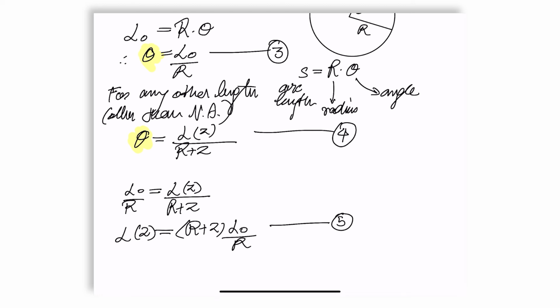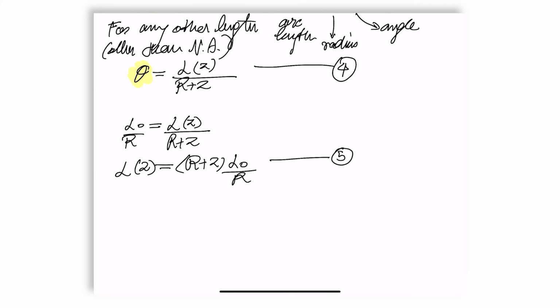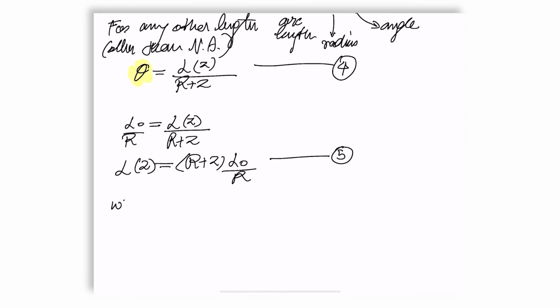So we of course are led by this expression for L of z to the question, what is the strain, which is what we originally set out to answer, by the way, is the strain epsilon at some distance plus or minus z from the neutral axis.